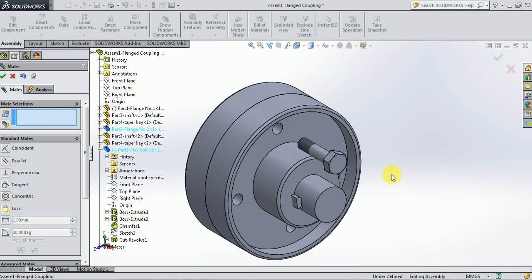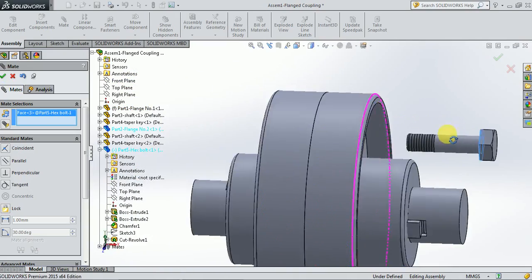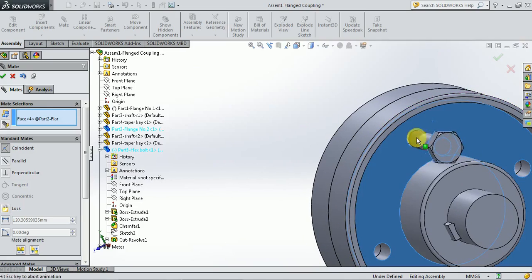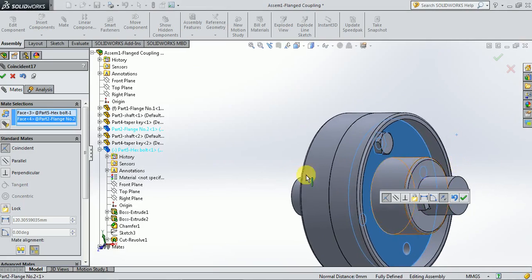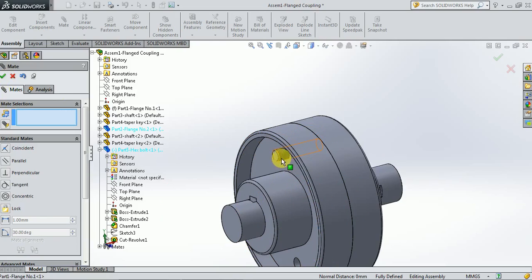Okay. So done. Then once it's aligned, I'm going to take this face of the bolt head, which will come in contact with this particular face. So insert it. Once it is inserted, you can see now the thread portion has come out here. For this thread portion we have to fix the which one? Nut. We have to turn the nut against this thread now, so that the two flanges will be rigidly assembled under the mechanical forces, because when we are turning the nut, it applies the compressive force onto the two objects, and they will be held together.